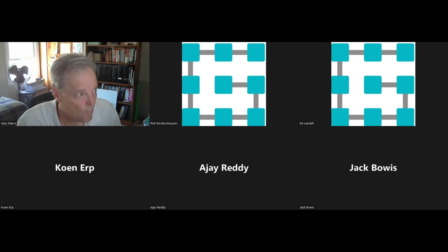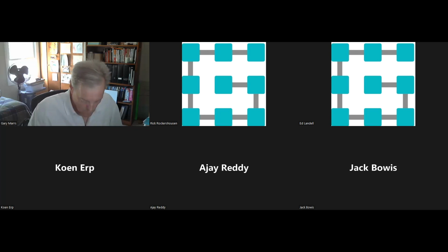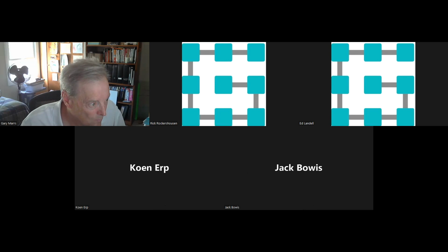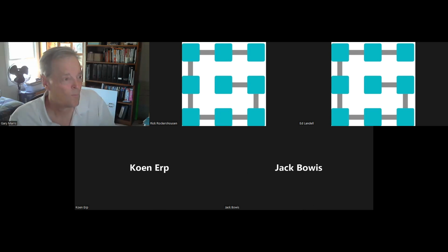I don't know, Ed, if you're on, if you can answer that. I guess my first initial thought is that PCAN-View is a protocol layer tool and is not looking at some of the problems Gary mentioned on the physical layer. So if you have issues with bus loads or error frames that are happening a lot, like there's noise or interference on the line, you can't really tell that with PCAN-View. You need one of those handheld tools that Gary went through there.